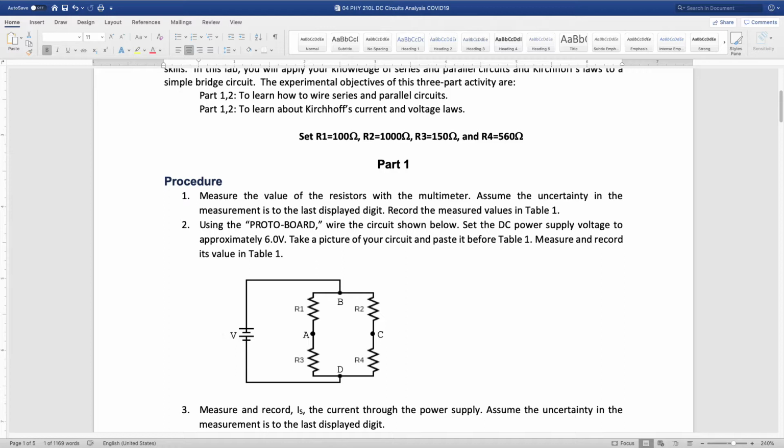Yeah, when I collected the data, I saw that small error, around 2%, maybe as much as 3%. Again, that's going to depend on how much current you have in your circuit. So you can always attribute that to the fact that your ammeter introduces a systematic error. You did it once with the ammeter in and then you took it out. But if you want to use the uncertainties based on the manual, then go ahead, you can do that.